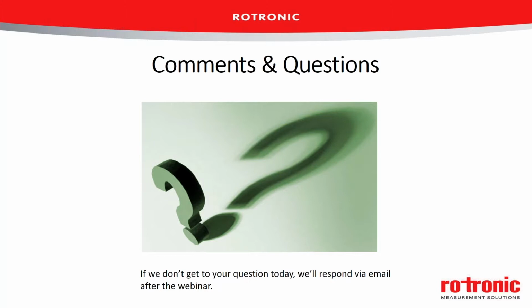I guess that's a fair question. We say they measure relative humidity directly because the sensor is changing according to what the relative humidity is. So rather than it measuring the dew point temperature or the wet bulb temperature, it's affected by what the relative humidity is, and that's why I say we're measuring relative humidity.